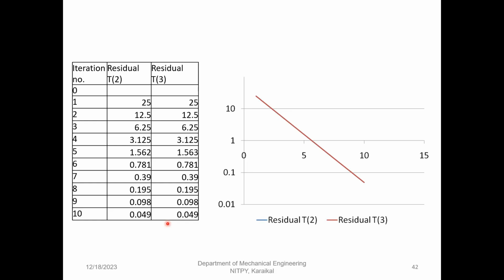If you have made some error, it may say the solution is converged, but you must look at whether the values really match what is experimentally observed, or what you are expecting. Residuals are just the difference of two numbers, and it can be misleading sometimes. I'll show you an example later.